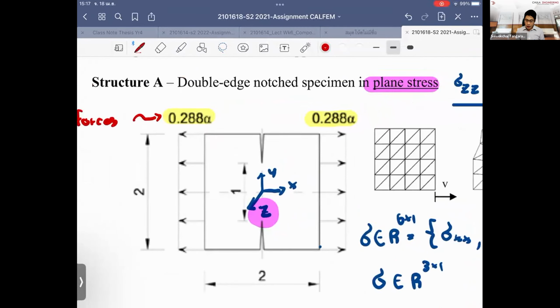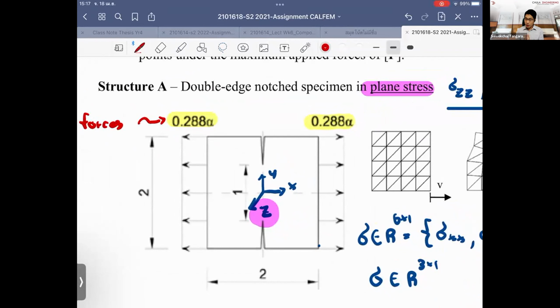What we have is a two-dimensional plane, in plane stress, and the problem is symmetric over two of the axes, over the x and over the y, right? In this case, you don't need to exhaust yourself modeling this structure in full. In full means you have to model it with the full notch. It is not quite a wise or smart way of doing this work.